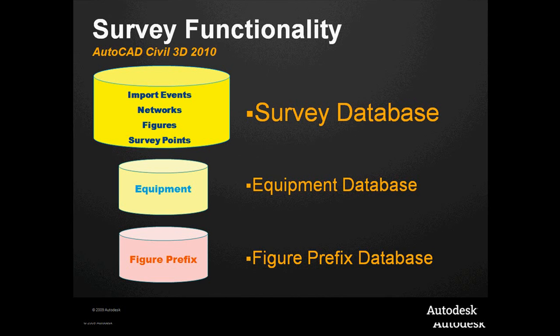At the same time, some of these things should automatically be used as break lines. So when I calculate a surface, I don't want to have to retrace these things to use them as break lines, or maybe some things should be break lines, other ones shouldn't, like an overhead electric line. I want to see line work, but I don't want it to represent my contours or anything like that. All right, so that'll be done through this guy.